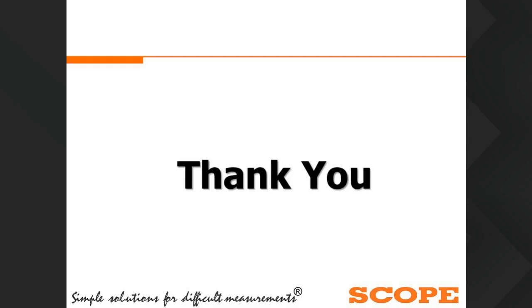But is any such time period mentioned in IEC for turns ratio or vector group detection, Kiran? Only for turns ratio, IEC 60076 gives it for the routine test. They have mentioned that this test should be done once in a year.